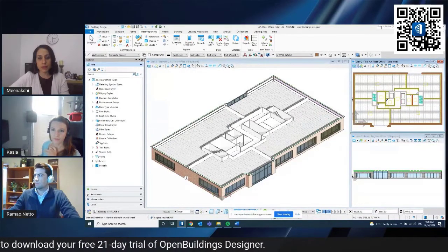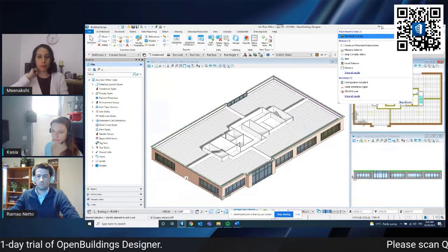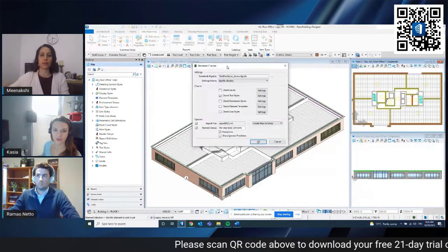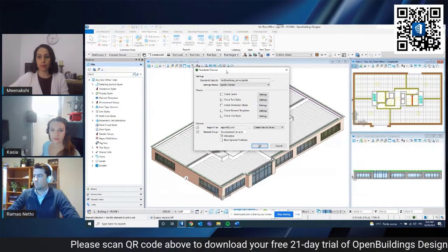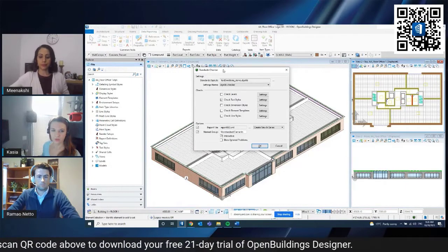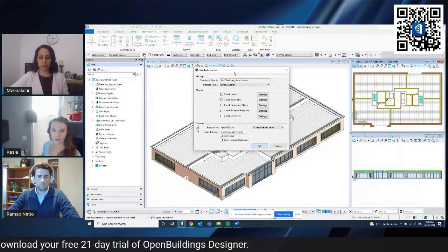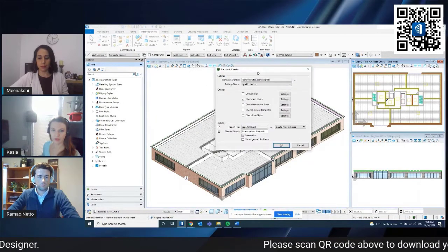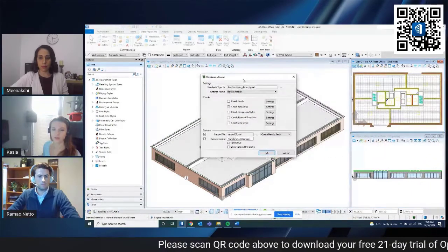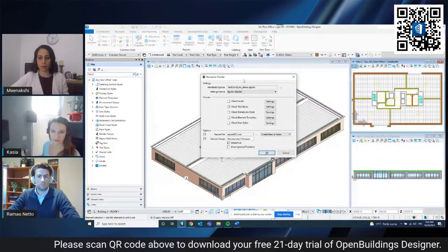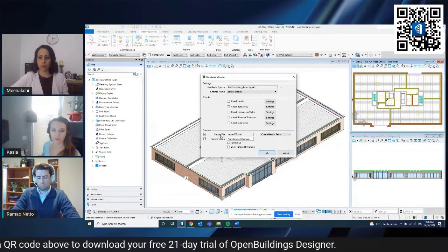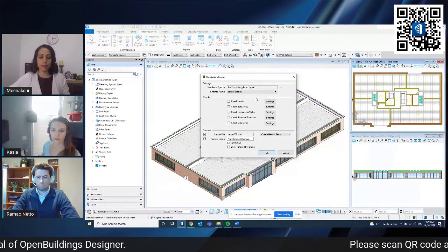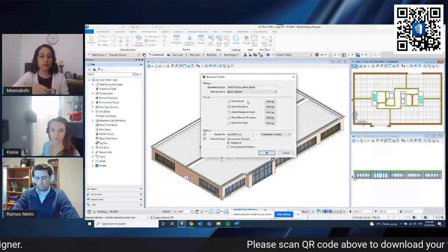So I can maybe start with this standards checker tool. If I just search in this search box, I can see the standards checker dialog. And this is exactly a tool that was created to check if we meet the standards we prepared, and we can then compare the file we're working on and see if we really meet those standards, and we will get a ready report from this check, and we will be aware of any differences in the standards.